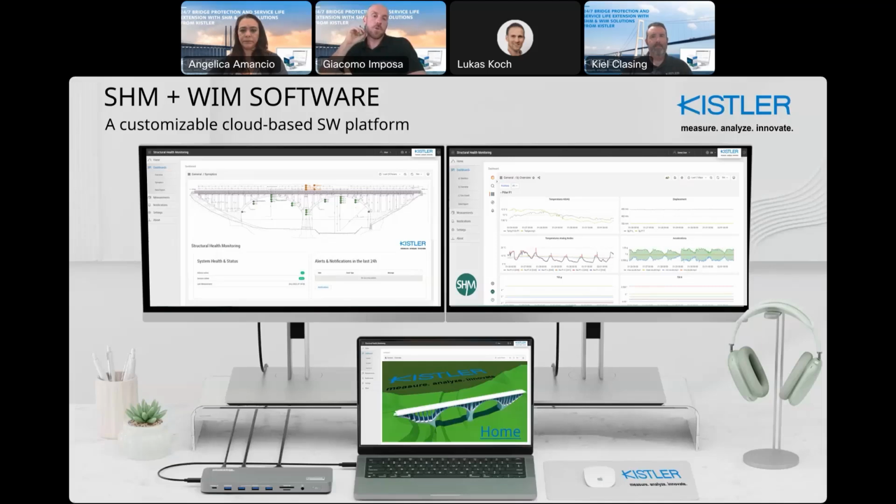In the orange dots, we have environmental parameters recorded by, for example, the weather station. While on the right side of the slide, you can see all the channels they are recording. We have temperature, acceleration, inclinometers, and so on. And in the smallest one, there is a digital twin representation of this bridge that we are developing with ETH Zurich.